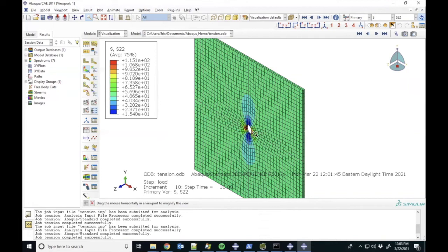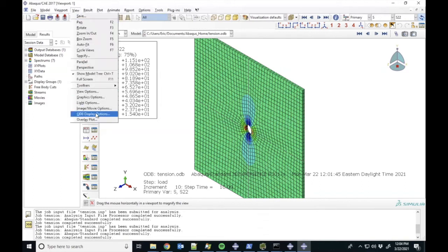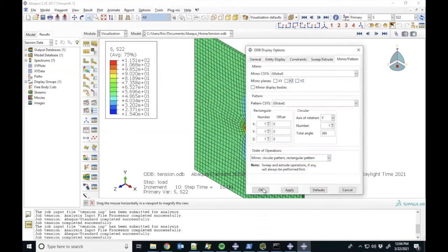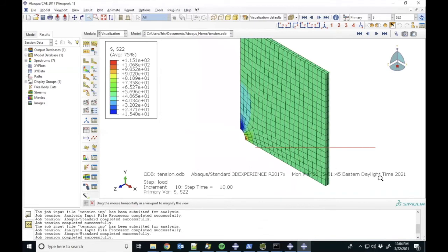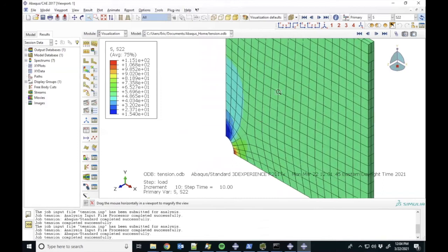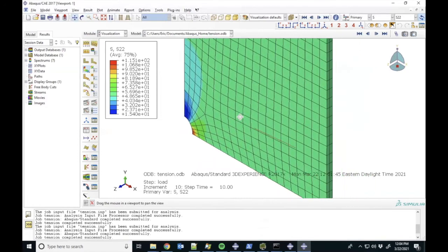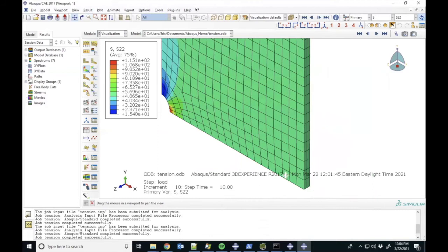But we can get a better look at the actual finite element approximation along that ligament compared to the analytical result if we export the distribution of stresses along that ligament and then plot it, doing some post-processing in MATLAB against the analytical result. So let's do that. Here, I'm going to get rid of these symmetry reflections and just show the actual simulation domain again. Let's zoom in and focus on that ligament from which we're going to be extracting the results. So this bottom surface.